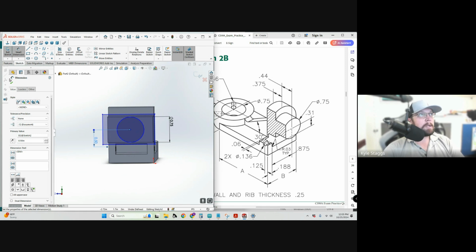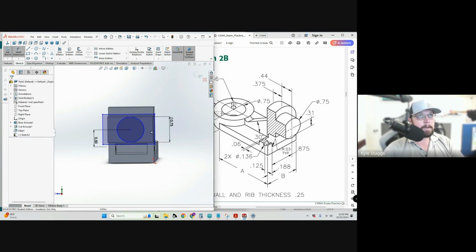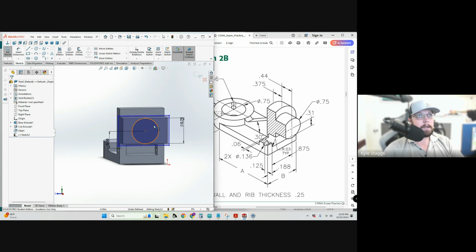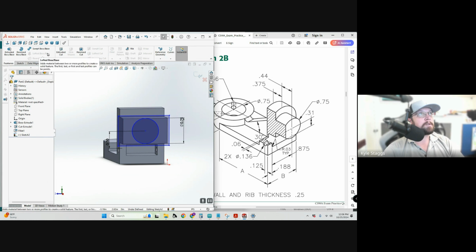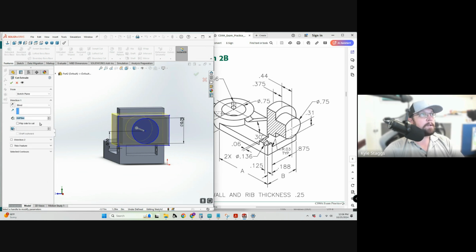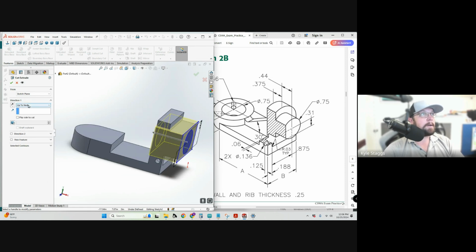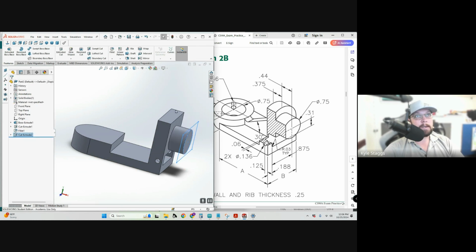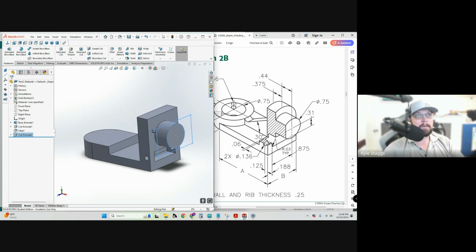So it won't be immediately clear, but I'll clarify what I'm doing here. This is a cookie cutter that I'm using to press the geometry I want onto that surface since it's a blank extrusion. It's a simple additive method like a stamp that's removing material. So if I do an extrude cut and I do up to next, up to surface, and I pick this surface, then I have my circle geometry, and I didn't have to work extra hard.